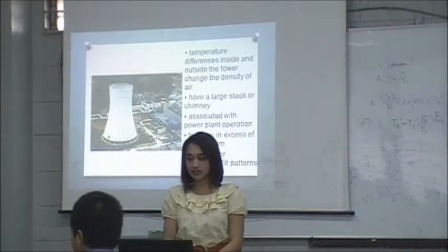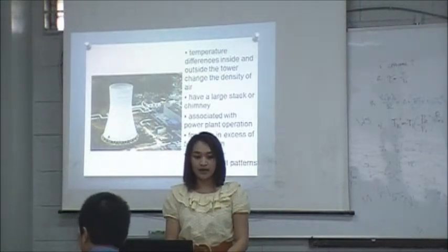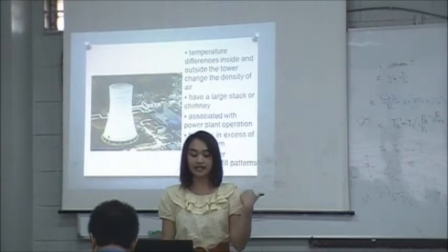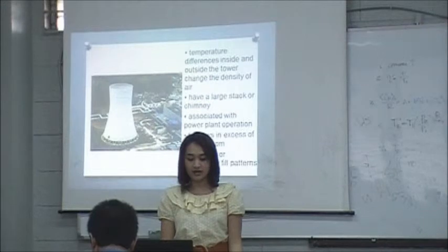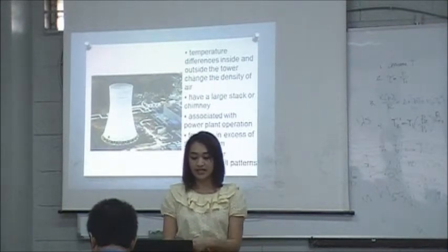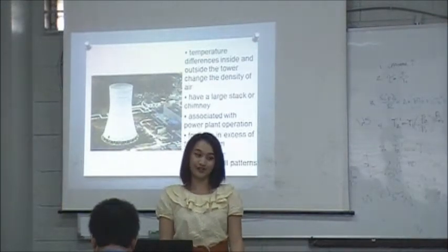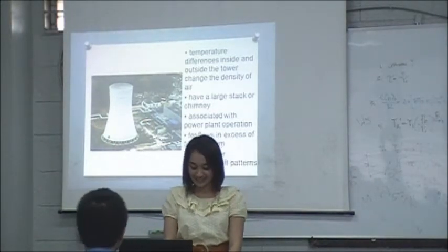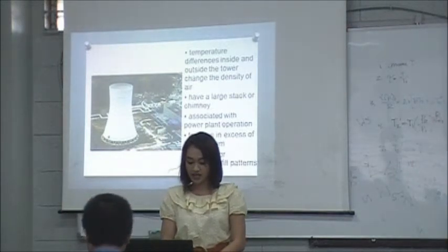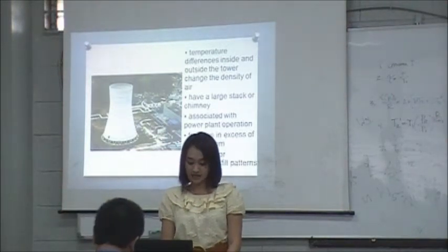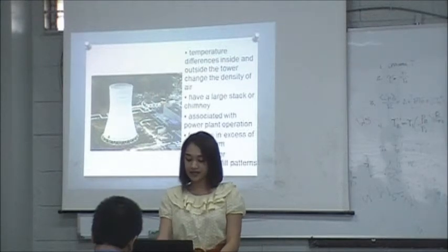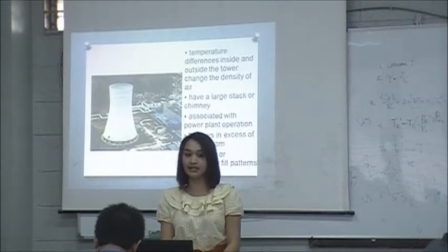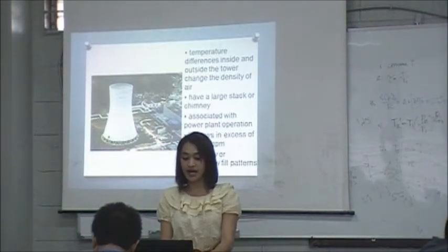In hyperbolic cooling towers, the airflow can be cross-flow or counter-flow, unlike in the atmospheric, where the flow is only cross-flow. In the cross-flow design in a hyperbolic tower, airflow rates are higher, therefore promoting improved air-water contact. It will operate at a lower head loss at the same capacity as the counterflow in the hyperbolic.